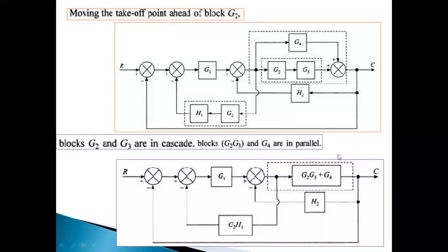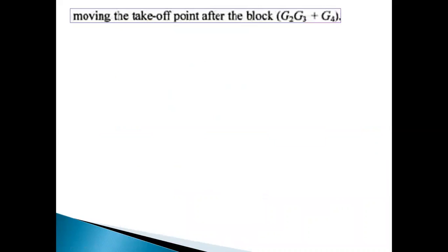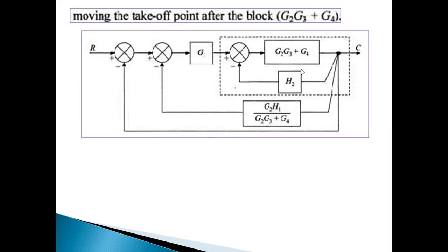Note down these figures. Okay. Now moving the takeoff point after the block G2, G3 plus G4. In this case, see here, the block 1 by G2, G3 is added at the takeoff point. We can match all these takeoff points.